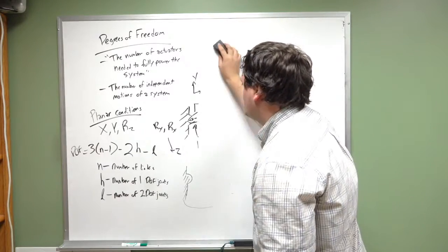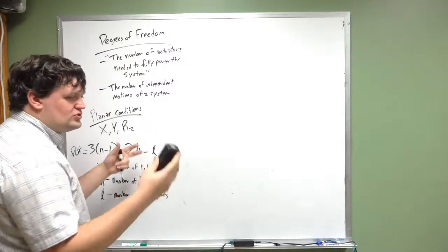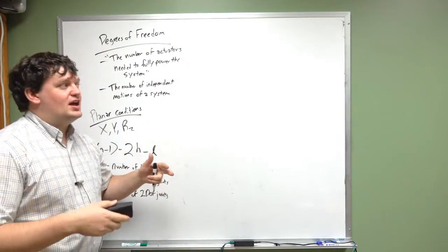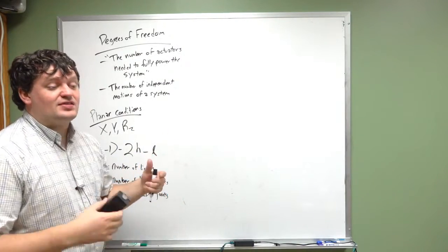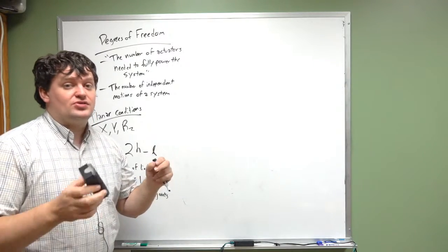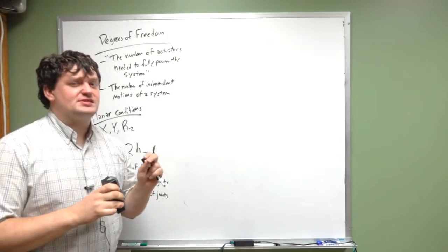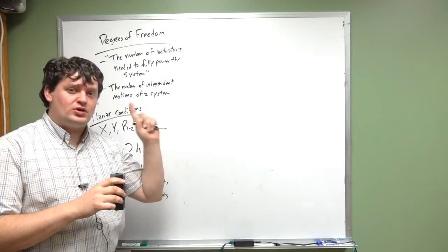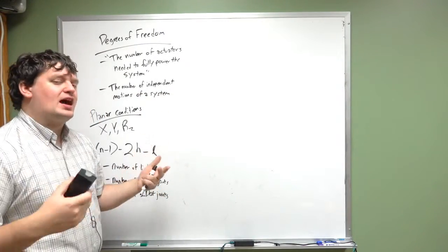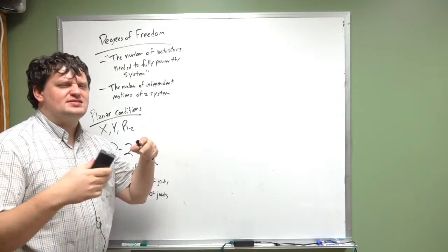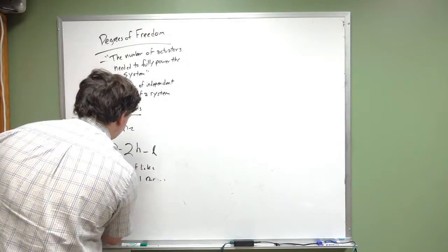Okay? Now what we're going to cover is you can do this for 4-bar systems, 4-bar linkages, have 1 degree of freedom total. Always do. You can come up with 5 and 6-bar configurations that do have 1 degree of freedom. Again, the benefit of a 4-bar system is that it has 1 degree of freedom, which means you have 1 motor actuator and you're able to control the output based on 1 motor actuator. So that is one of the nice things about having a 4-bar system, is that it does have that 1 actuator type output system. Okay?